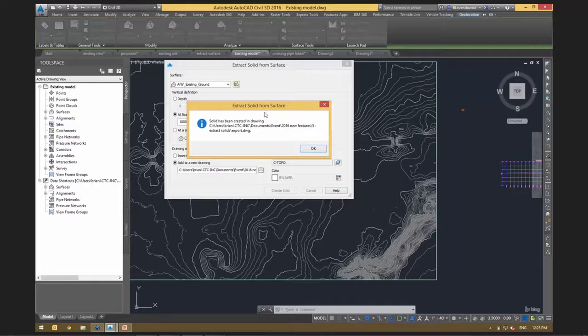I mean use some of the tools on the Manage ribbon to import styles and settings, and then also use Design Center to bring in AutoCAD content. It's not too bad a process. It's maybe half a day or a couple hours, depending on the complexity of your template, to migrate that. But I see corruption and problems starting to show up when you've migrated for too many years forward.